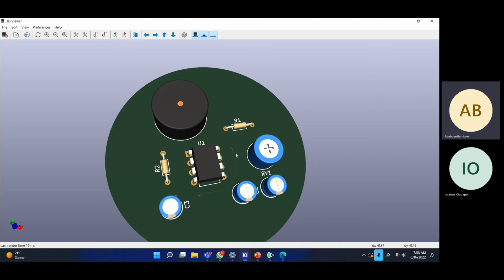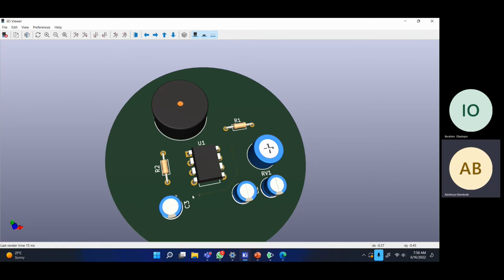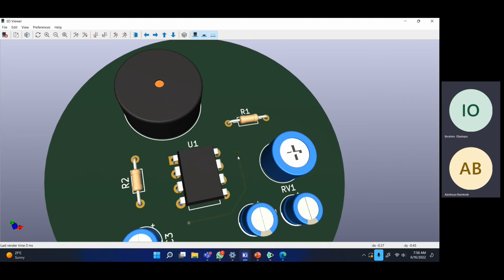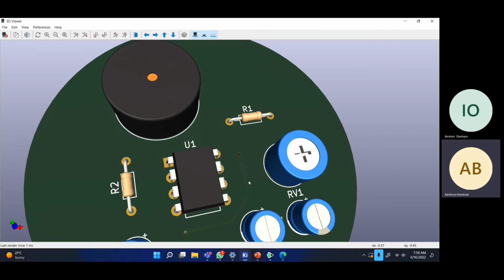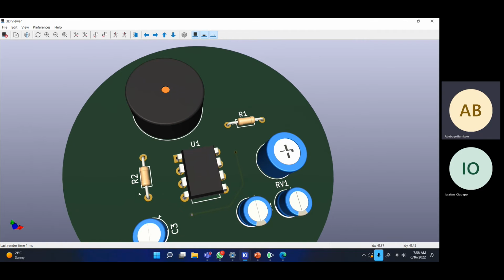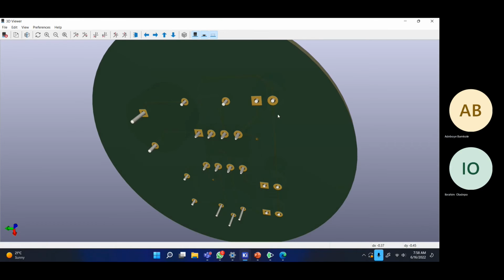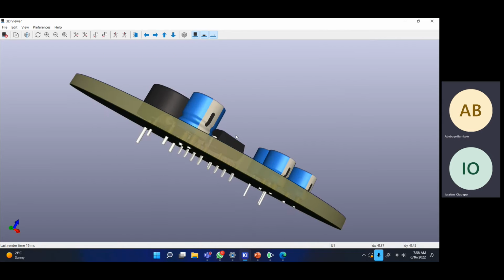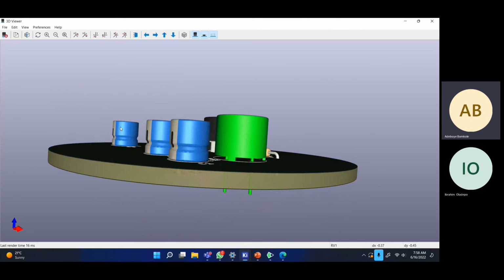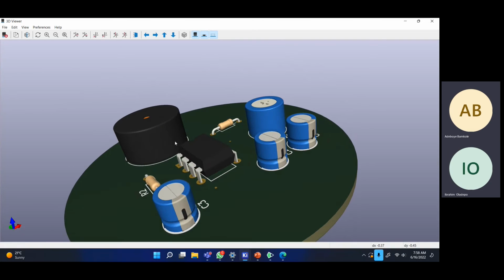So if you are using a one-sided PCB, can you see this kind of connection I have here? You can actually use a wire to do it. You can just put the wire here, solder it, and then put the wire in the other place to solder it. Oh, that is an excess of unnecessary wires. Yeah, I get that. You could use a connector or something like a header. You plug it in, exactly. Yeah, you can use stuff like that.